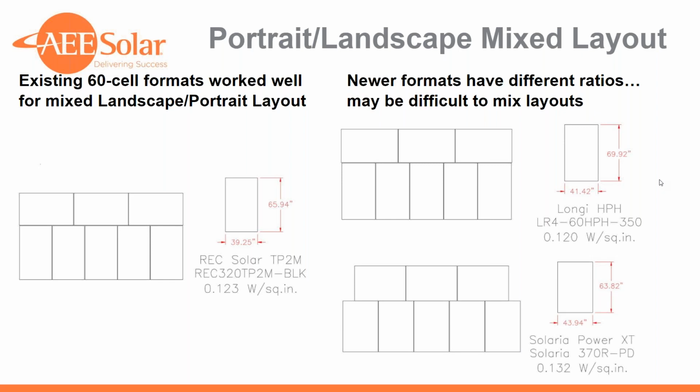I think Glenn did plan out the inner module spacing there for mid clamps, because I do see some gap between these modules. On something like a Solaria, it's not going to work out that well because they've got a different shape, and modules come in all shapes and sizes. So lots to think about for what would work best for your business.